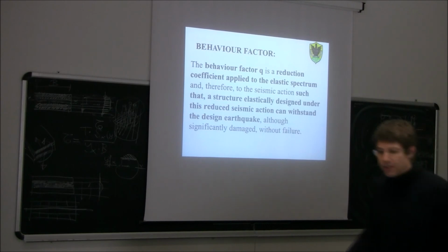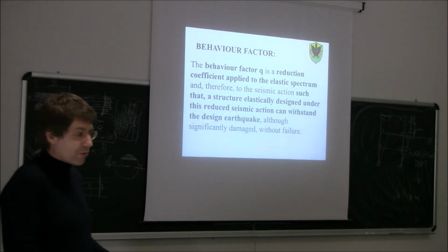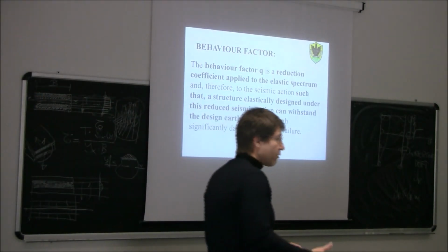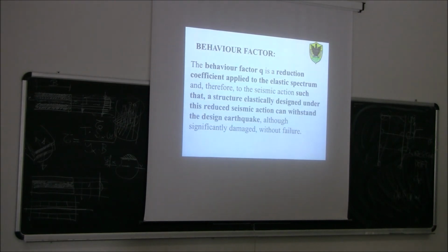So in other words, it's, if you want, a simplification of a problem which would be complex, should be treated as a nonlinear problem. We say, okay, a nonlinear analysis is too complex, so I always do an elastic analysis under reduced seismic forces, which accounts for the fact that my structure can dissipate energy. So in the end, my structure will survive the earthquake, even though it will be very much damaged.